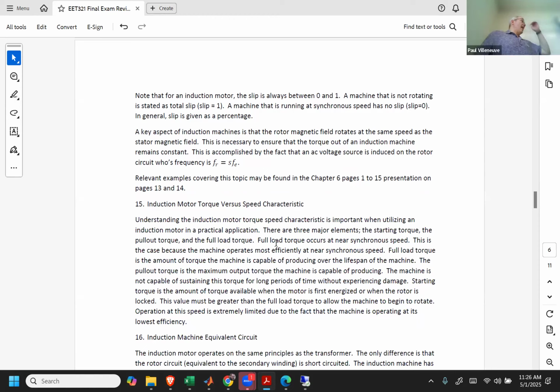And because you had a rotating magnetic field that was induced from the stator currents, you generated an AC waveform on the rotor. And the frequency of that rotor, you could determine based on the slip and the applied electrical frequency. And that had to be AC because your rotor field always has to operate in sync, or at the same speed, as your synchronous field or your stator field, because again, you want that constant torque. So the fact that you got something rotating with an AC waveform on it means you can get those to spin at the right speed.